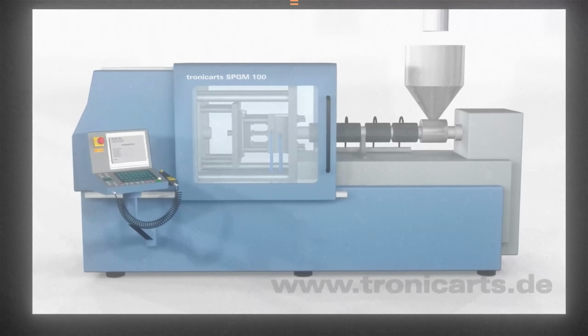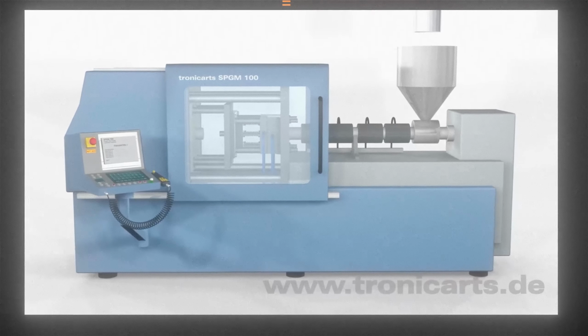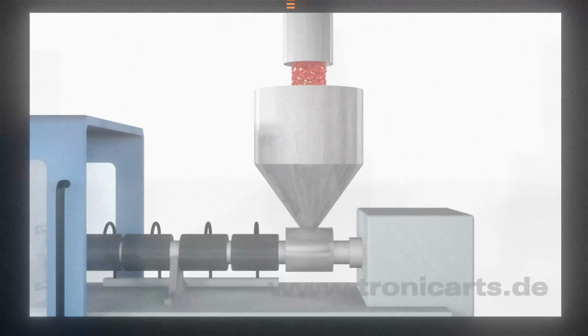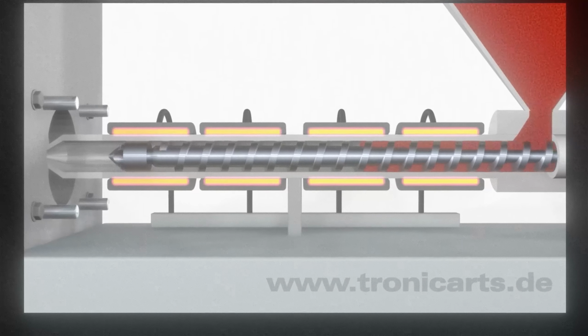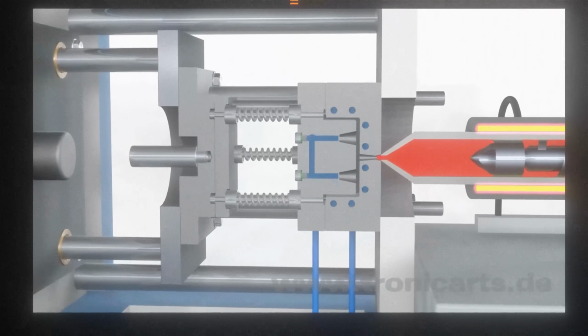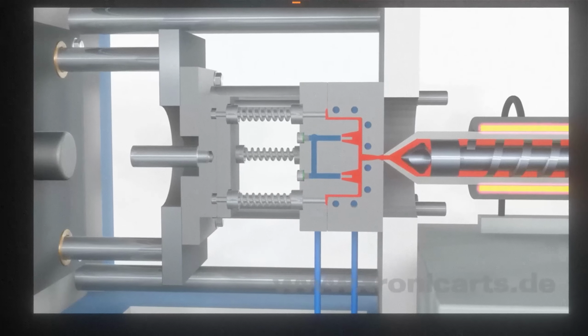Injection molding. Forming complex products. After compounding, the pellets are sent to the injection molding line. The process includes: 1. Feeding into the injection molding machine. The pellets are loaded into the hopper and fed into the heating cylinder. 2. Melting. The material is heated, turning into a fluid melt. 3. Product molding. The molten polymer is injected under pressure into a mold, where it takes the desired shape, for example, a bumper. 4. Cooling and removal. The product is quickly cooled and hardened, after which it is pushed out of the mold.